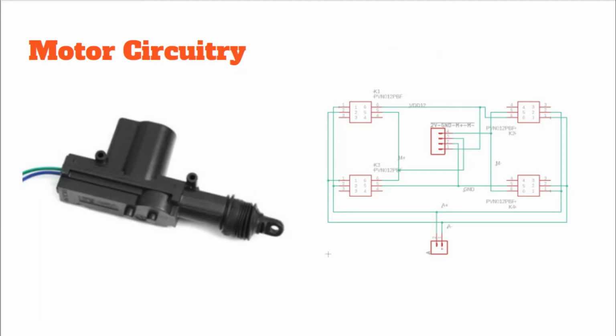The main component of the striking mechanism design was the linear door lock actuator, which would push the drumstick into the drumhead at a high speed and force. These motors required high current to work as intended, which was implemented in an H-bridge fashion using 4 relays. Each motor was driven by its own H-bridge circuit.